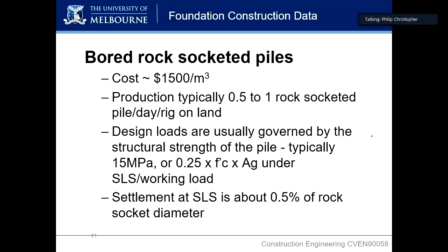It just takes time. If you're drilling rock, you don't drill rock really fast either. That takes time as well. So it is a slow process. However, it's unmatched in terms of capacity. If you need big loads and you want to socket them into strong rock, there's no choice.